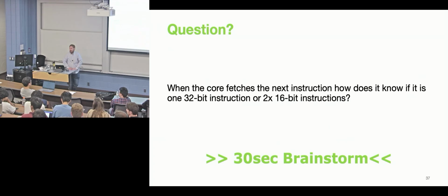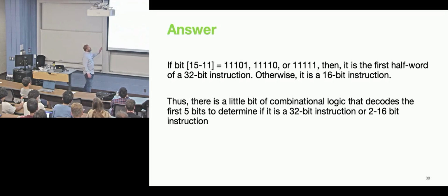Something like in the instruction coding it says... Yep, nothing too magical. So ARM basically says if these are at the beginning of your 32-bit word, if these are at the highest bit locations, then that's going to be a 16-bit instruction. Otherwise, what is it? Oh, it's going to be a 32-bit. Otherwise, it's going to be two 16-bit instructions. So basically, they're just using some basic encoding structure for that.